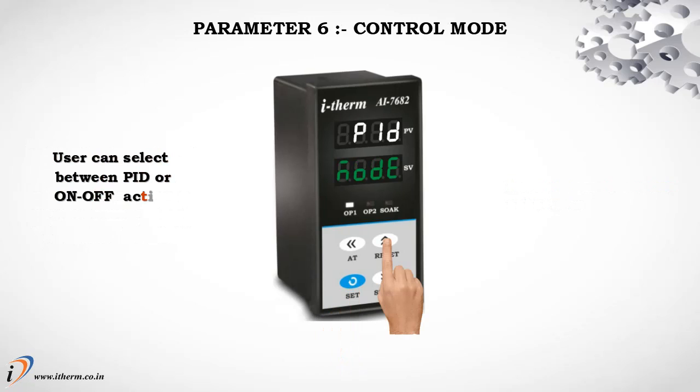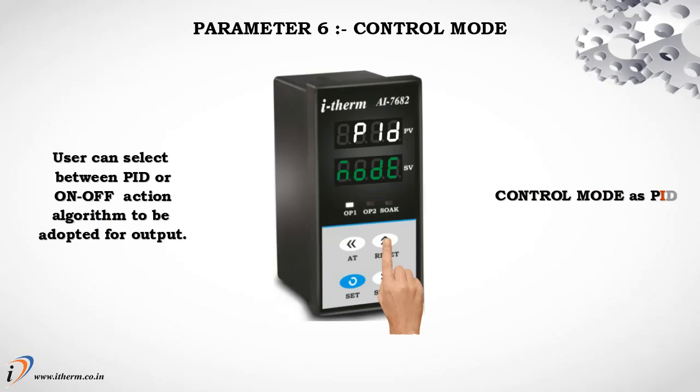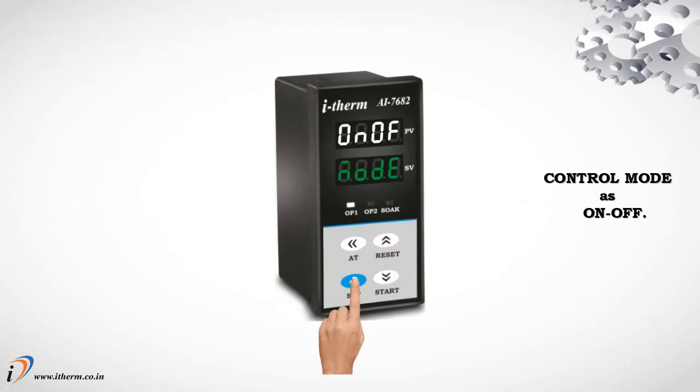Parameter 6, Control mode. User can select between PID or on-off action algorithm to be adopted for output. Control mode as PID. Control mode as on-off.